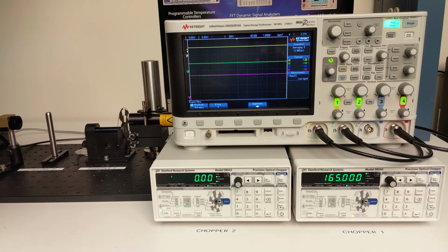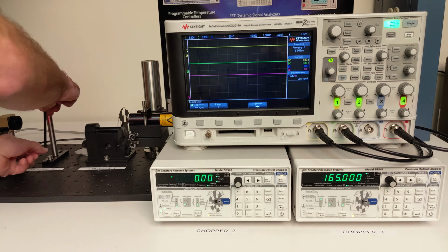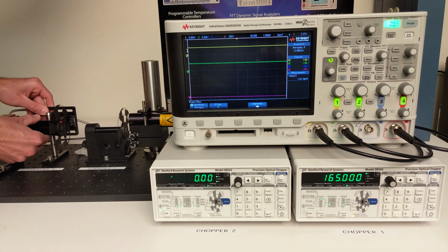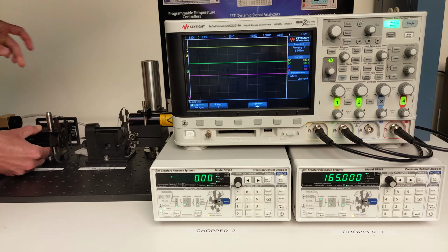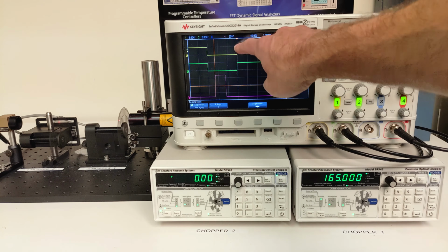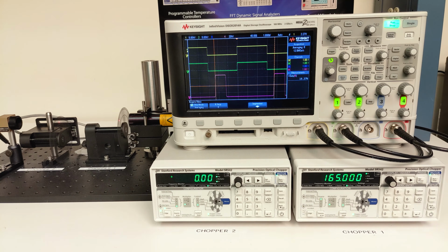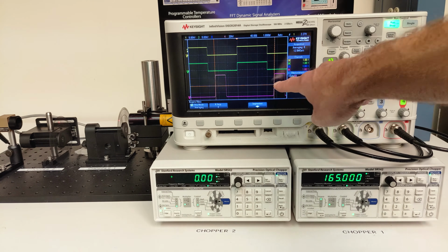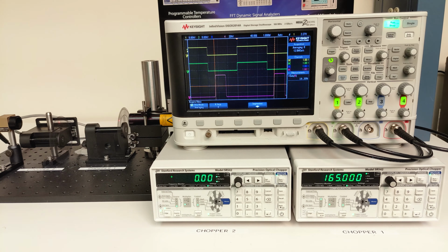However, if I change the mounting of motor 2 so that the beam passes at a different location around the blade track, you can see that this statement is no longer true. The reference outputs still appear phase aligned, but the photodiode output no longer represents the logical AND of these signals. In this case, the coincidence of the reference output rising edges is not a useful indicator of 50% duty factor, and you'll have to use the photodiode output itself while tuning chopper 2's phase.